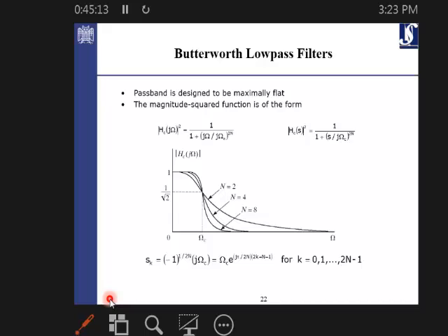The larger value for the n, the sharper can be the transition band from the pass band to the stop band. It should be sharper, and it's much closer to the ideal case. On the other hand, you have more computational cost, and it's also getting closer to instability because it's IIR.